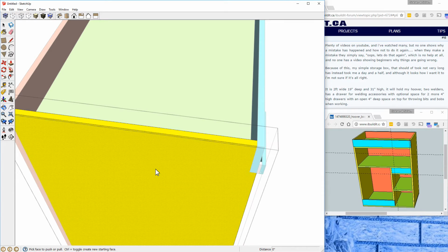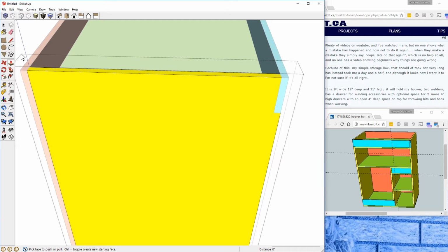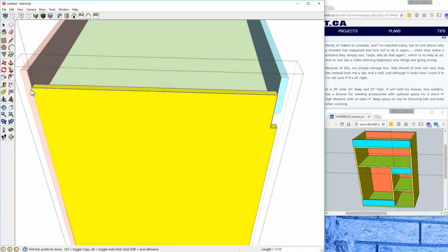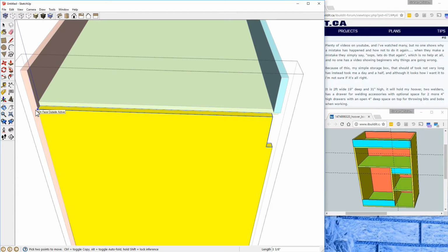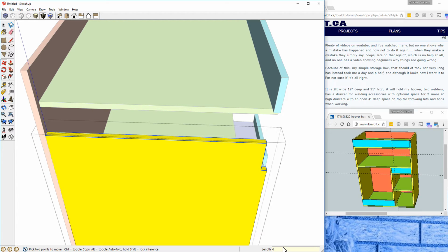What I need to do is to select all of the parts of that panel that need to move. So by extending from the left hand side and dragging the select box, it's actually selecting everything that's fully contained within the select box. So that allows me to select the top face and the notch side and the bottom of the notch all as one thing, and then move all of them, and I'll move them 6 inches. So that's one side moved.